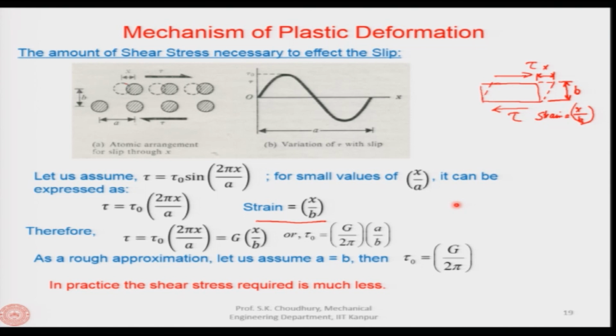So, to pull those big, fat, higher diameter and heavy cables bodily is very difficult. So what the laborers do is they make a loop, I will take the pen, they will make a loop kind of a thing like this, all right. And they push this loop so that, being round, it can actually roll, okay. So instead of frictional mu, that is the coefficient of friction, it will have the rolling friction, which is much less, as you understand that.